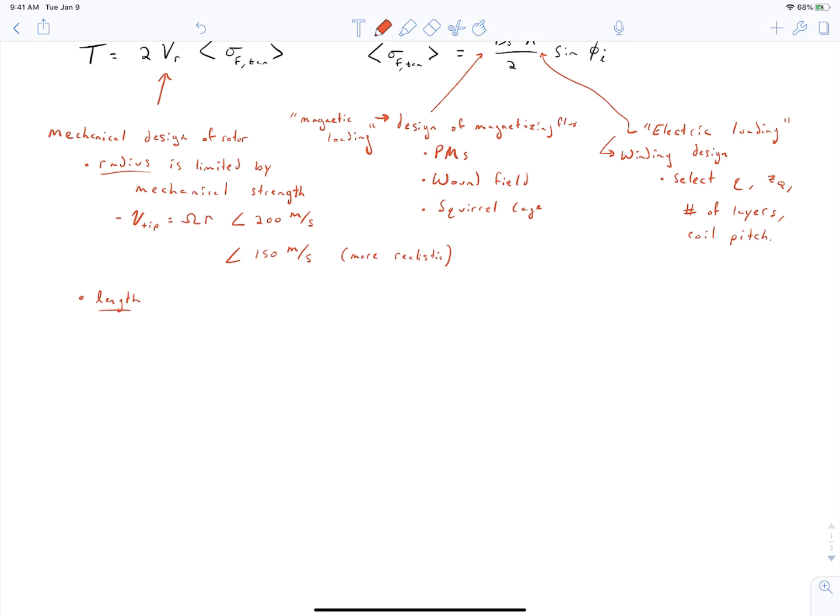But basically, when you have a long, narrow rotor, you start to get a standing wave appearing on your rotor at certain speeds, and that is a problem. It can lead to vibrations, it can lead to bending modes where your rotor actually becomes flexible, and this can cause failure in your motor system. So typically motors are designed so that they only operate below their first critical speed.